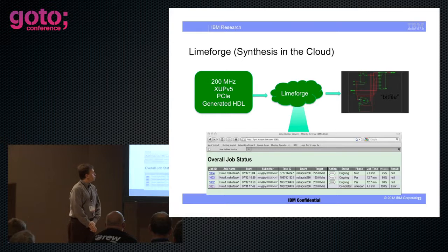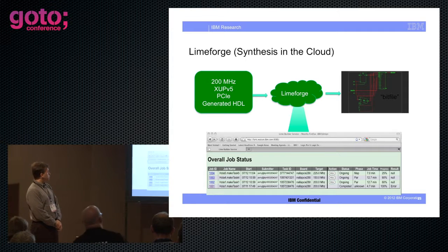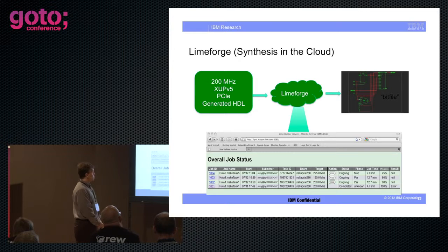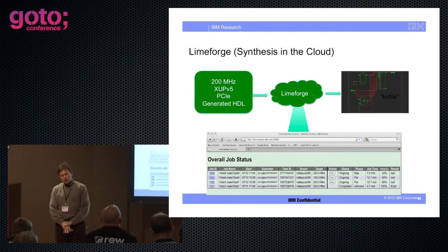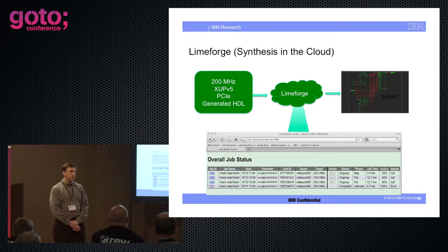So in order to compile a Verilog file or a VHDL file down to a circuit, you run a synthesis tool. This is a vendor-supplied tool, which basically lays out the logic, does the design, and tries to satisfy clock constraints and layout constraints and floor planning and come up with a design. So this is learning yet another tool. This takes a very long time.